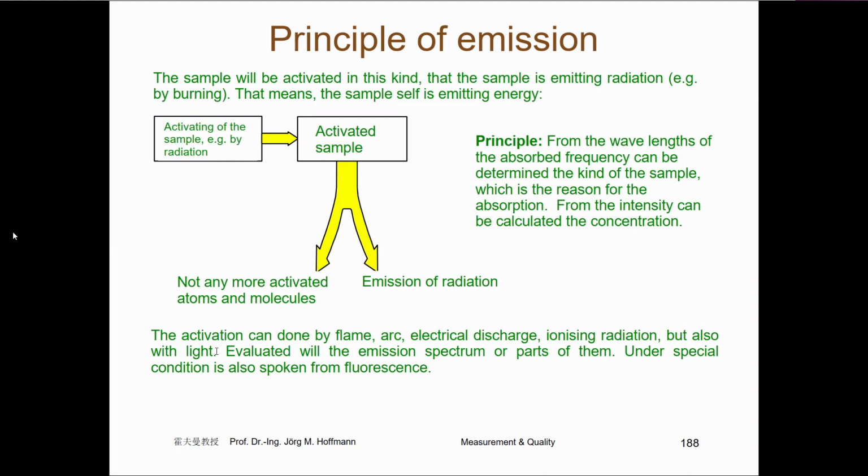When you irradiate oil with ultraviolet light, you get light back in the range of blue light, so that you can very easily check whether there is oil in this liquid or not. You irradiate with ultraviolet light, you see nothing of the ultraviolet light, but when blue light occurs, you know there is oil in this liquid.